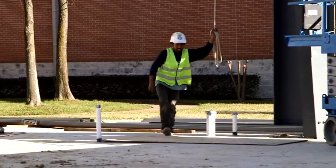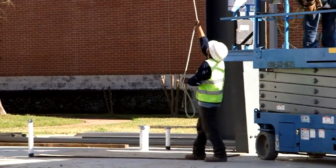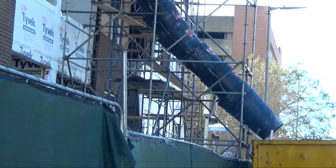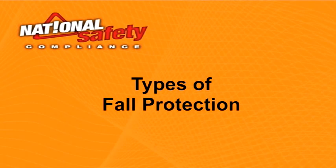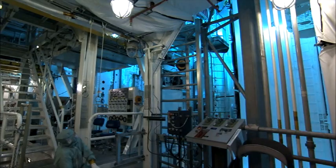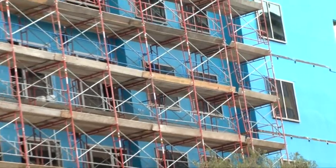To protect employees from falling objects, employers must ensure employees wear hard hats and erect toe boards, screens, or a guardrail system, or erect a canopy structure, or barricade the area to which objects could fall. OSHA has established fall protection requirements for many specific situations, such as hoist areas, runways, areas above dangerous equipment, wall openings, repair pits, and scaffolding.